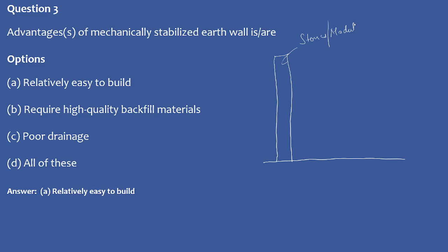This wall is further wrapped with some geosynthetic materials, as you can see. Then this is the reinforcement available with us, which is placed alternately with some compacted fill. So here we are introducing the compacted fill.